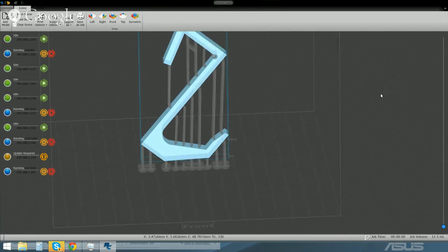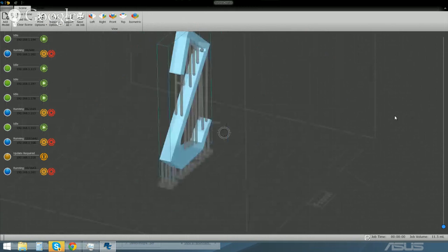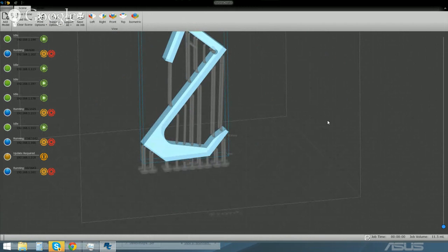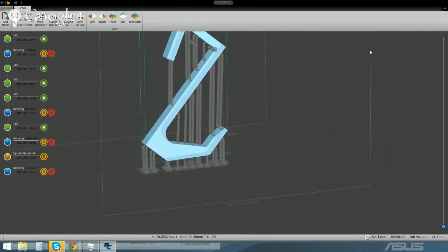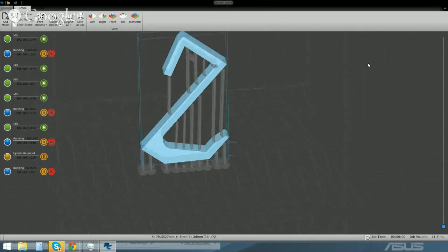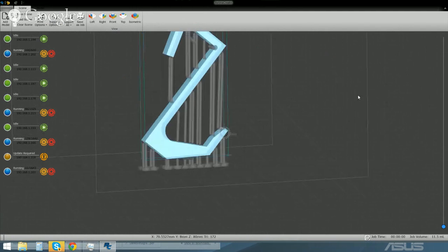It will still draw critical supports, whether or not that value is lowered. So these 2 supports will still draw even if the min interior support length is increased. But these ones are less important because they're just helping reduce strain. They're not absolutely critical to pick up a floating part.